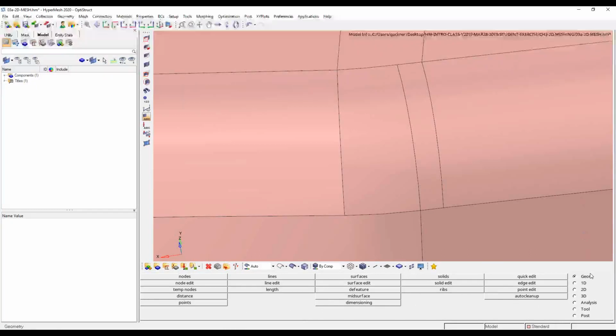An example of this geometry preparation could be what we saw yesterday of extracting that mid-surface out from a thin solid or a plated solid in order to use these shell elements with. What I'm going to do here is not extract a mid-surface. We've already seen that this is already infinitely thin. I'm going to start turning off surface lines or merging multiple surfaces in order to reduce the total surface count. I'm not deleting surfaces. I'm not removing area from the part geometry file. I'm simply going from 100 surfaces that combine to be 100 square millimeters to being 50 surfaces that still combine to be that same square millimeter area.